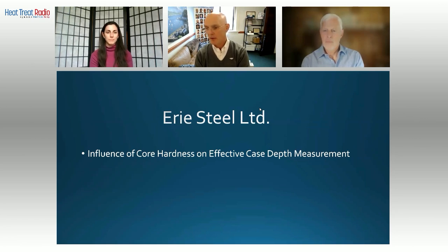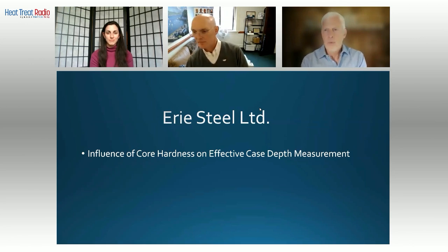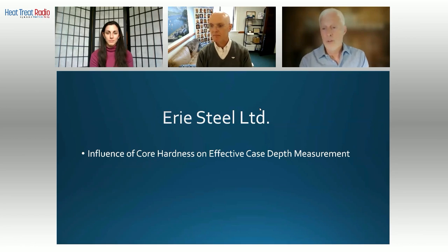So, Michael, we are open to learning here. We're going to get a little bit into the weeds today, and we're going to talk about some things specifically metallurgical. For those involved in high volume production carburizing, we know that consistency of results is extremely important. Not just important in that we have the process centered, but ultimately it has something to do with dimensional control. Specifically with gears, if the output from the process is not consistent, then one of the things that's going to suffer is the dimensions of these parts.